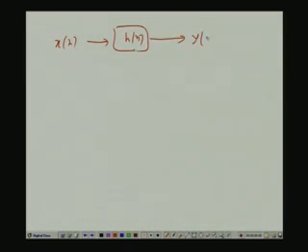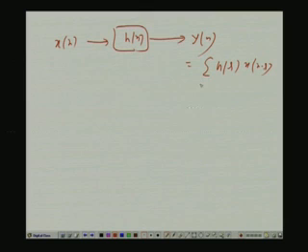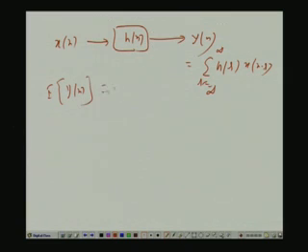And once again you can see the response of linear systems and all that, we can do it very quickly. Suppose x[n] goes through h[n], a linear shift invariant system, and we get y[n]. y[n] is nothing but the discrete convolution, sum of h[r] x[n minus r], in general from minus infinity to infinity. So, what is E of y[n]? Input is WSS. E will go inside, working directly on x, into E of x[n minus r], input is WSS.